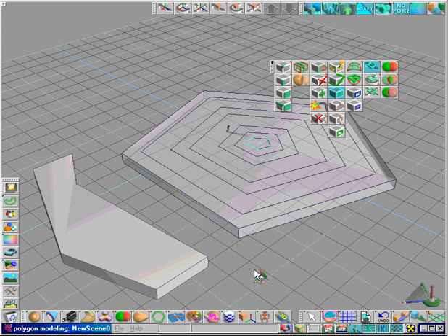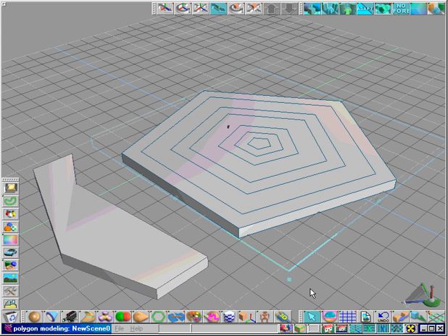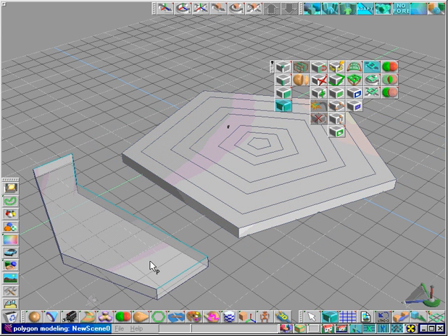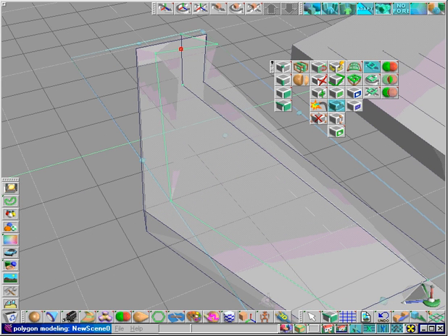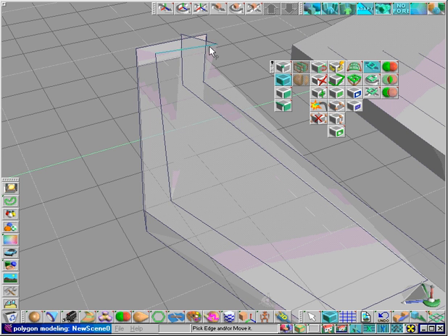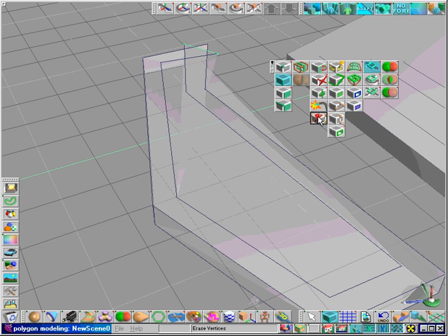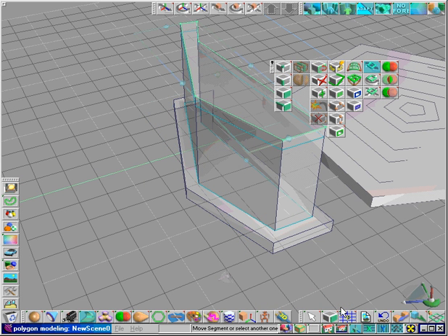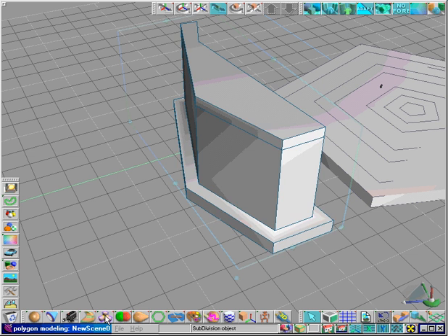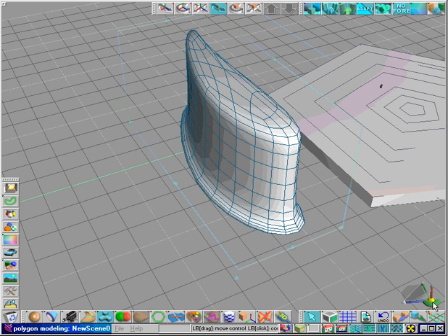Note that all the new outlines are in the same plane. Also note that some faces will cause crossed geometry lines, like this one. This is not hard to fix, either by deleting a point, or in this case adding a point where we want the corner to go, and deleting the unwanted edge. We can sweep the edited face and SS the object with no geometry problems.